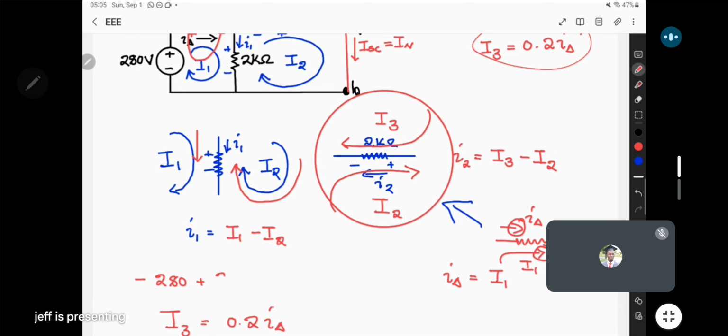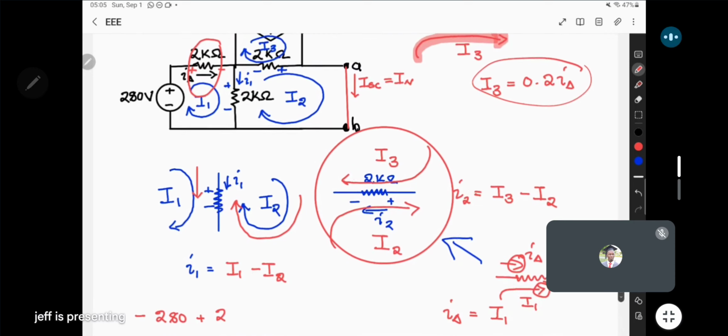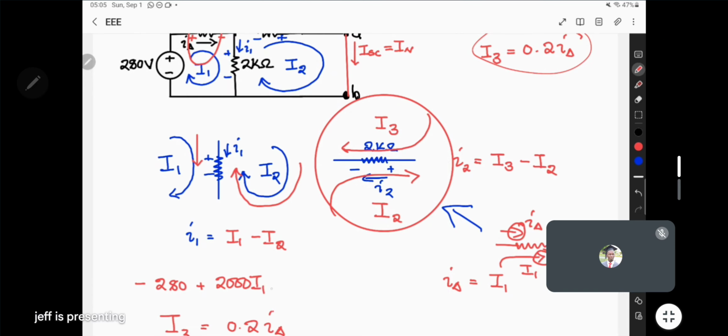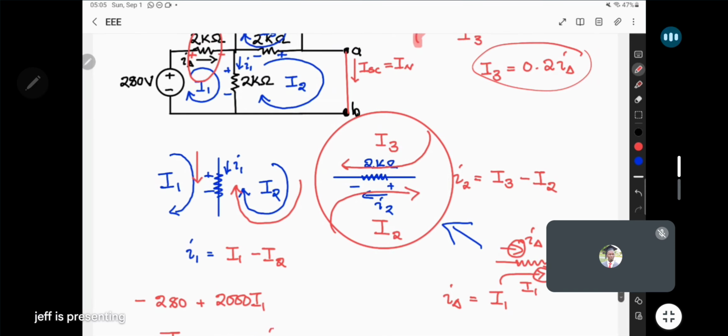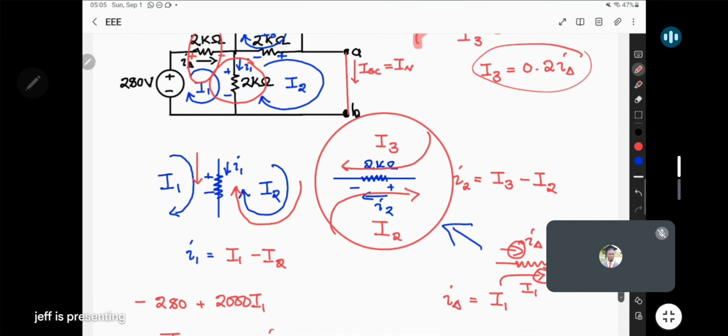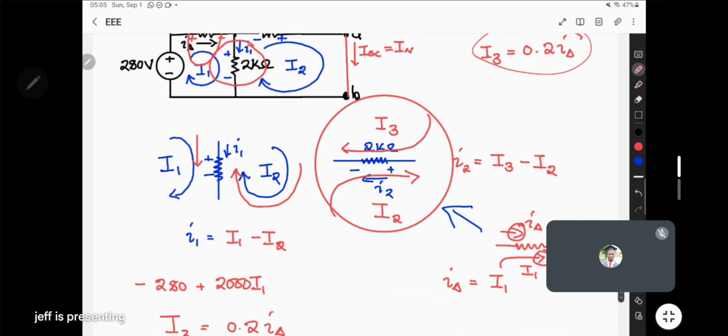So this is why for that one, it's going to be resistance times current. It's going to be 2 kilo ohms. Now that's kilo, so I want to use the ohms. So 2000, and then the current there, mesh current I1. By the time we reach down here for this one, the resistance there, first we're finding it positive. First we're going to have plus the resistance there, 2000. The current passing in it is branch current I1. But remember what branch current is equal to.